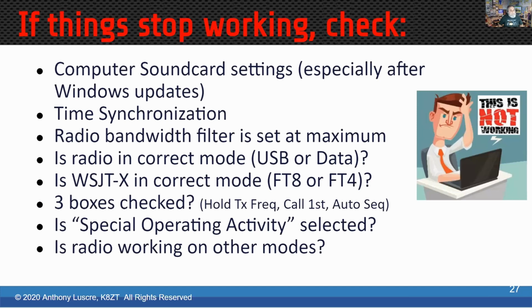This is a rather long slide, but this is a checklist I put together for a couple of friends I've helped set up over the years. Basically, these are all the things to check before you call Anthony on the phone for troubleshooting. So, computer sound card settings can change on Windows, especially when Windows does updates. Time synchronization software may stop running, or you may not have installed it in the first place. Some radios have a habit of switching bandwidth, and you want the bandwidth filter to be set at its maximum. The radio needs to be in the correct mode. Depending on the particular radio you're using, it might be in USB, upper single sideband, or in data mode if there's a data mode on the radio.